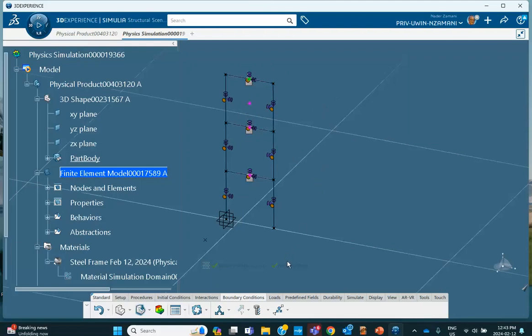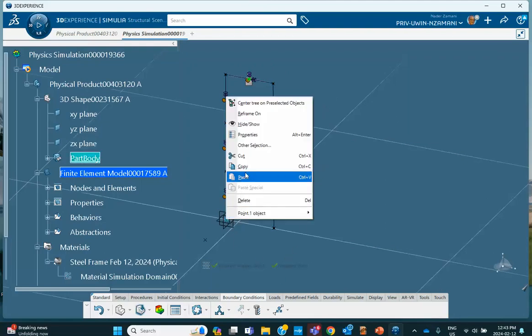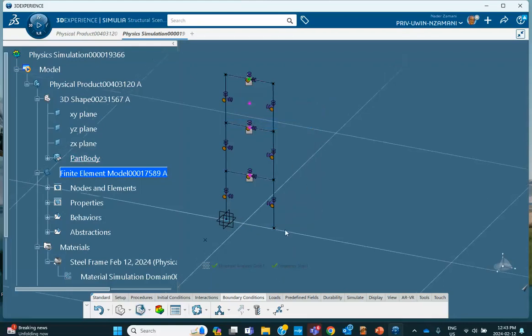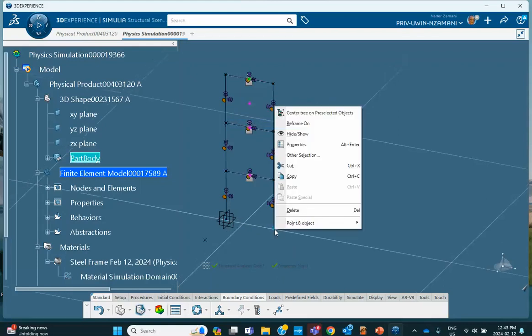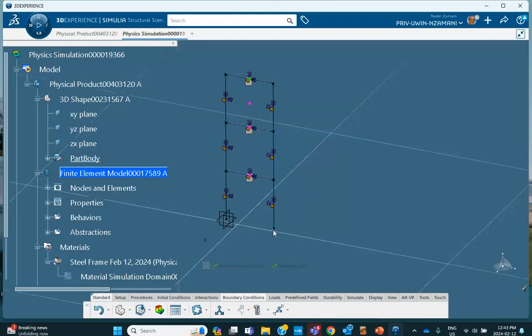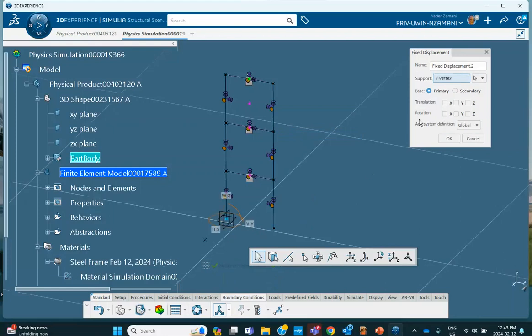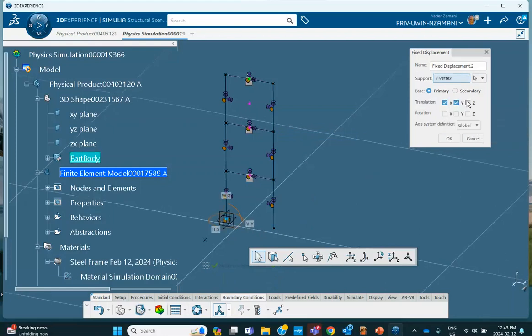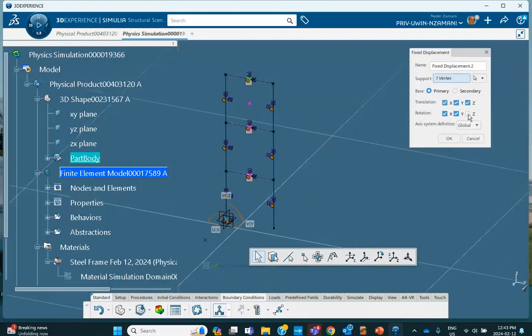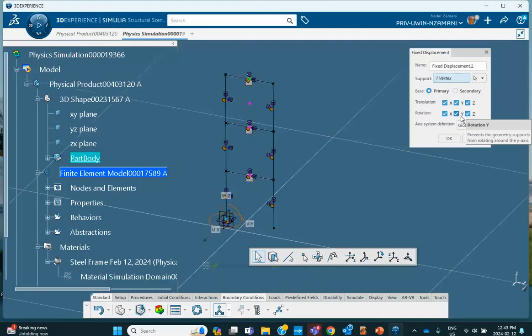So you should prevent those rotations. Now, these bottoms are clamped, so let me hide this point because I want to make sure that I don't inadvertently put a restraint on these points here. I can put it on vertex, but not on the point. So again, fixed displacement, you select this point, and because it's clamped, all of them are 0. I mean, basically these two rotations, and this already comes from what we just did, and we do 2 of them. Both of these are clamped.